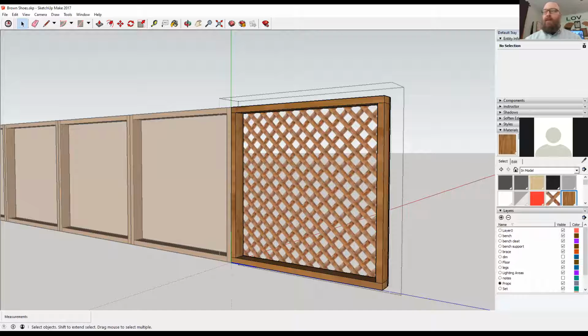I know in Ellie's notations, there was a note about how do we attach it to the floor. Fortunately, in both of our spaces, we have properly built stage floors that have an expendable top layer and a good hardwood bottom layer. So the way I would attach these to the floor is by putting screws directly through the bottom into the floor.